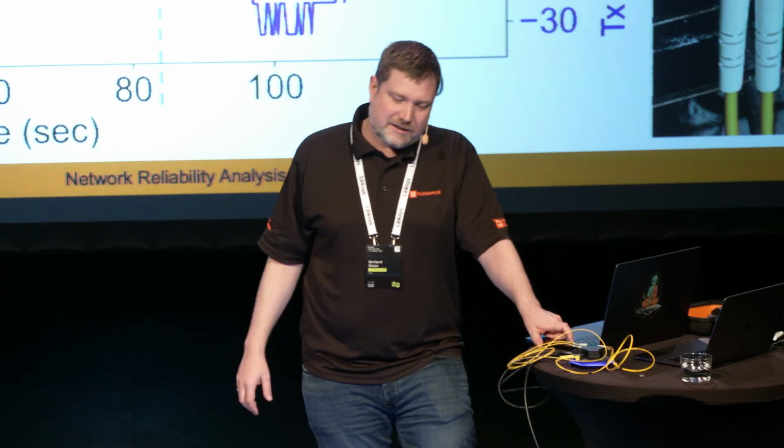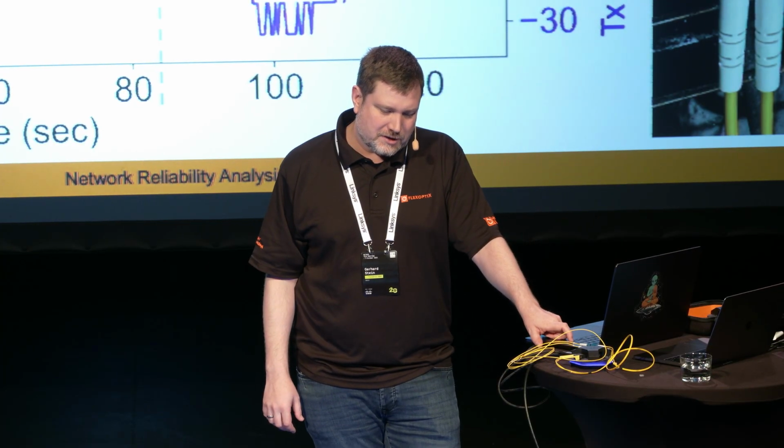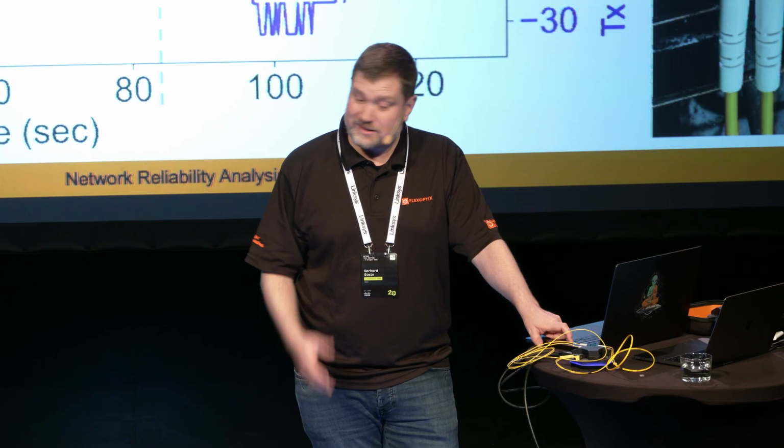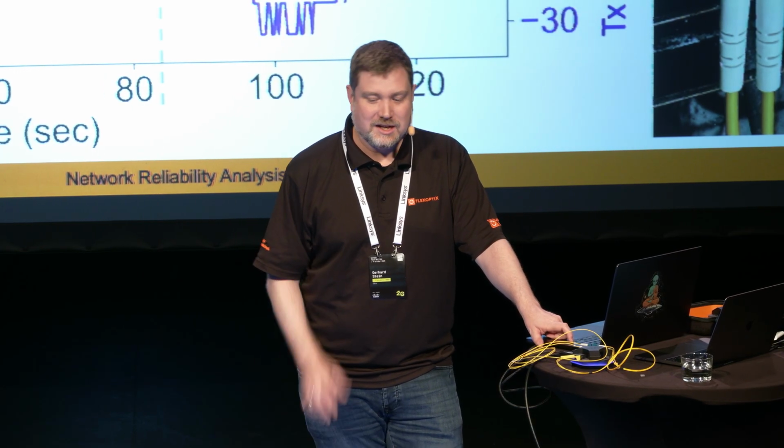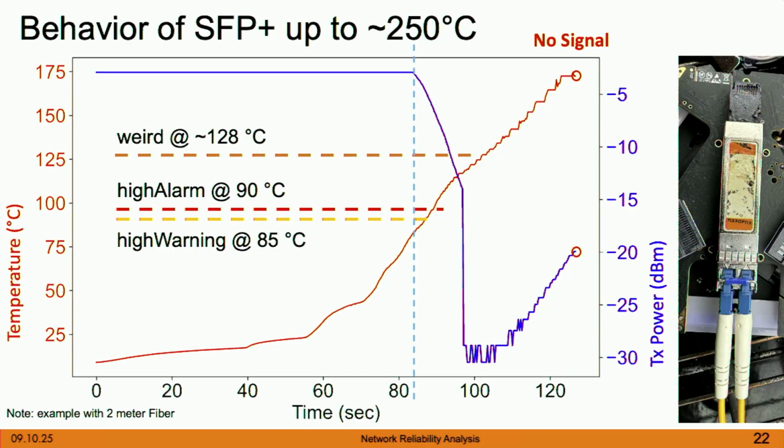But anyhow, we lost the signal, we went beyond, and what happened here was we really destroyed this transceiver. As you can see, not even the label is readable anymore. The FLEXOPTIX survived it. It's still doing more or less well. The port behaves a little bit weirdly, but there's still contact. But this transceiver, forget it. What happens? The Rx signal goes way down. It's still something you can read. You could assume it works somewhat, but don't use this transceiver anymore.